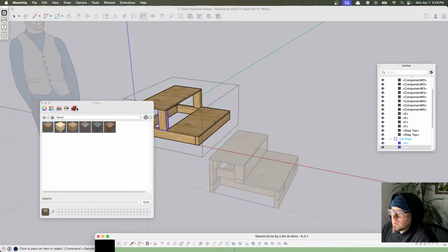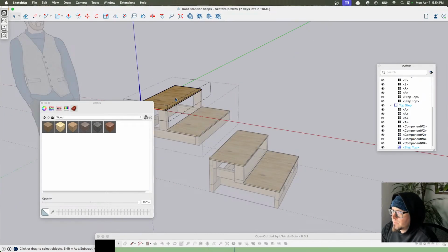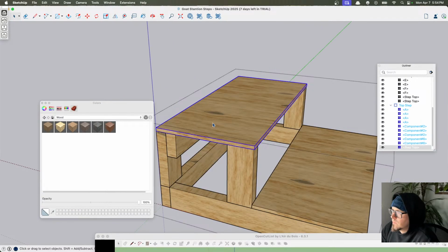I'm going to delete all the default thicknesses in here, as we're just going to have this. Now, depending on how you buy your lumber, it could come in 6-foot or 8-foot sections. It doesn't really matter. I'm just going to set mine up in 6-foot sections here. And if you have any length oversize, width oversize, or thickness oversize, you can add those parameters as well. I'm going to assume mine is all 0, so I don't have any oversize there. And we can give this guy a name. I'm just going to call this the 2x2, let's just call it the legs. Okay, you can go ahead and hit apply.